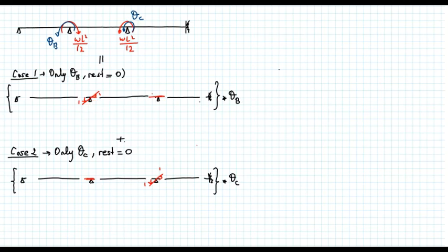So I'm saying that in order to create that rotation, I need a moment. So I'll call it K_BB. And in order to keep this rotation equal to 0, I have to have another moment here. I'll just say this is equal to K_BC. Likewise, I need a moment here. This is K_CB to keep that rotation equal to 0. And I need this moment to create a unit rotation at C, and I call that moment equal to K_CC.